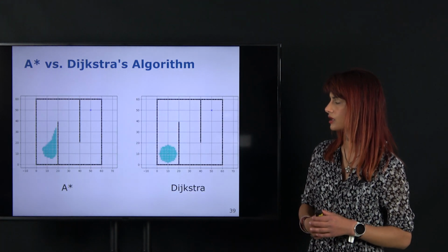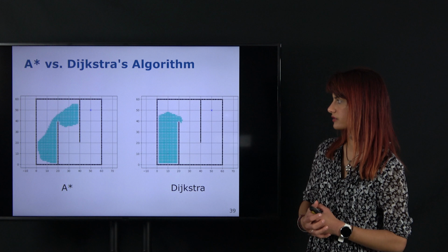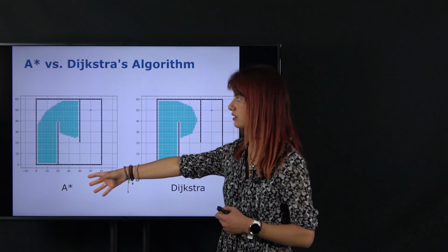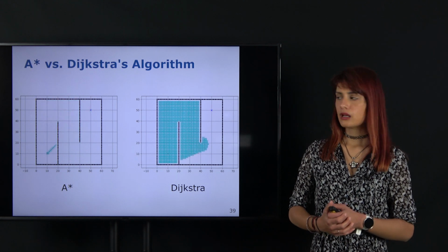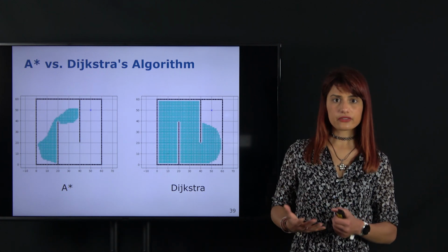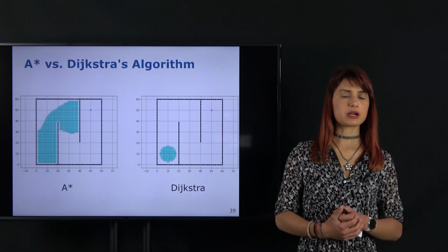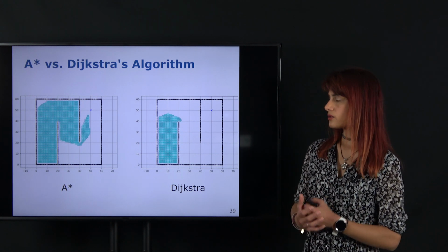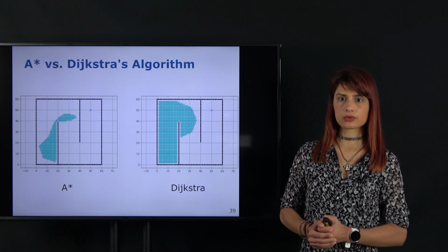And finally, an animation, just to consolidate these ideas of A-Star and Dijkstra in the same environment working together. And here, again, we see Dijkstra spreading uniformly, whereas A-Star is much more directional due to the heuristic, which drives it faster towards the goal. And so if we have these types of problems, and we care about efficiency quite a lot, then A-Star is the one that offers these benefits by the use of the heuristic value. And it's just important that the way in which we specify the heuristic, and if we care about optimality, then we do need an admissible heuristic.